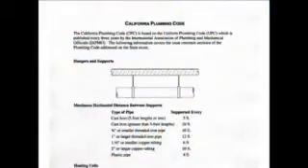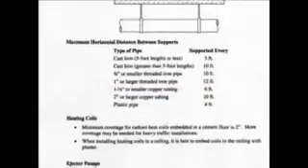At this point, we're going to start covering things a little bit more in detail. We're starting with the California Plumbing Code, and these are the summaries of code requirements that tend to occur on the state exam. Let's take a careful look at them. In the middle of the page, there is a list of some 7 different types of pipe. The 5th type of pipe, a 1.5 inch or smaller copper tubing. Note that that needs a support at least every 6 feet.